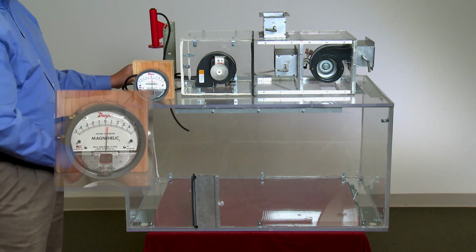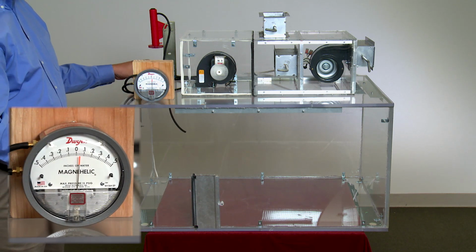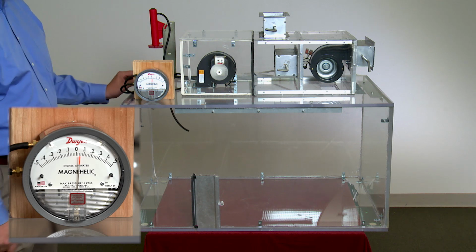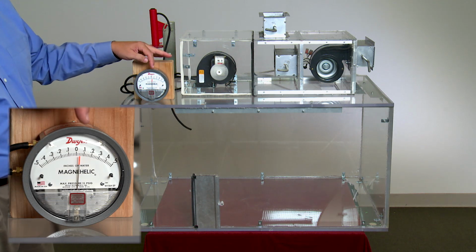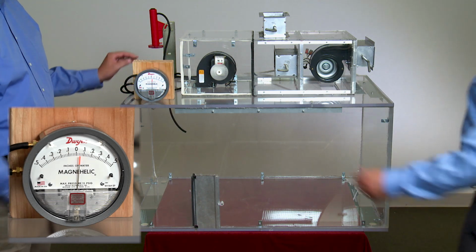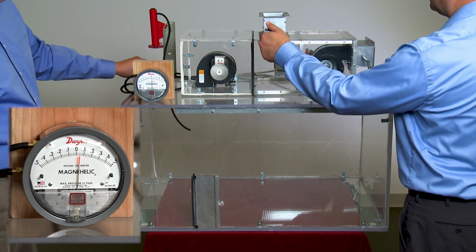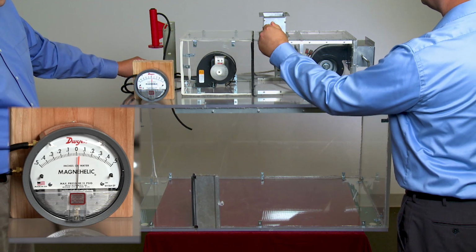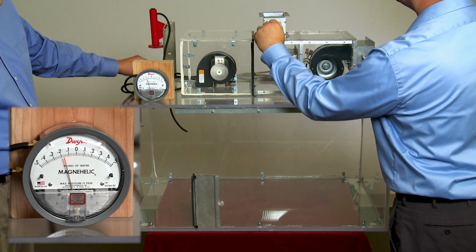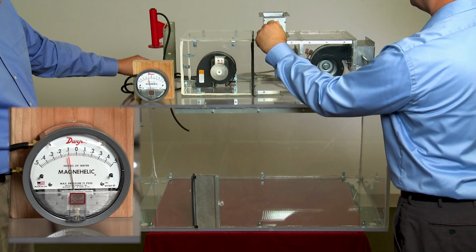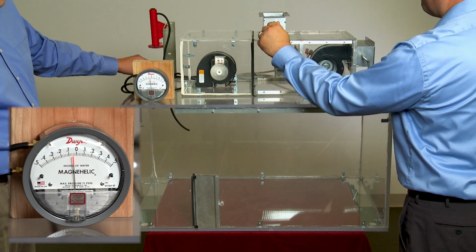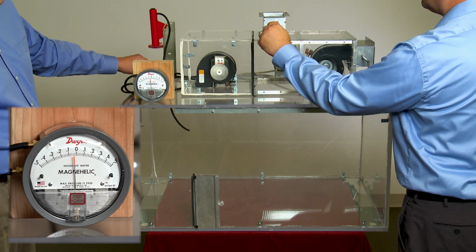Right now, the speed of the relief fan has been adjusted to maintain building pressure at the desired set point, which is 0.05 inch of water in this case. Now, Eric will modulate the outdoor damper further closed to simulate demand-controlled ventilation. You see that the building pressure starts to go negative as the system brings in less outdoor air. But I respond to this by slowing down the speed of the relief fan until building pressure is again slightly positive at our desired set point.